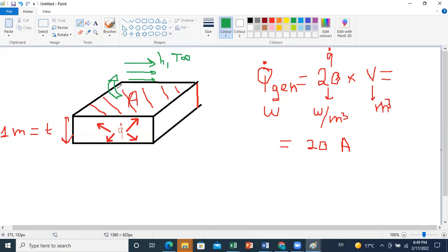Now, if you represented your flux towards the environment, and you put this as Q dot convection, then you should say that the convective flux Q dot convection in total over the whole area is equal to, since we are just representing by one flux, we can put it as big Q. So it's the total exchange, by considering the flux per unit area times the area. And here also I will put big Q dot generated.